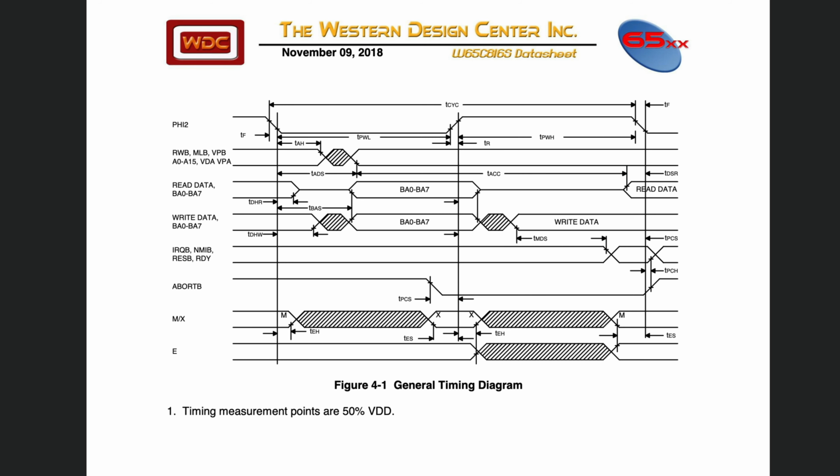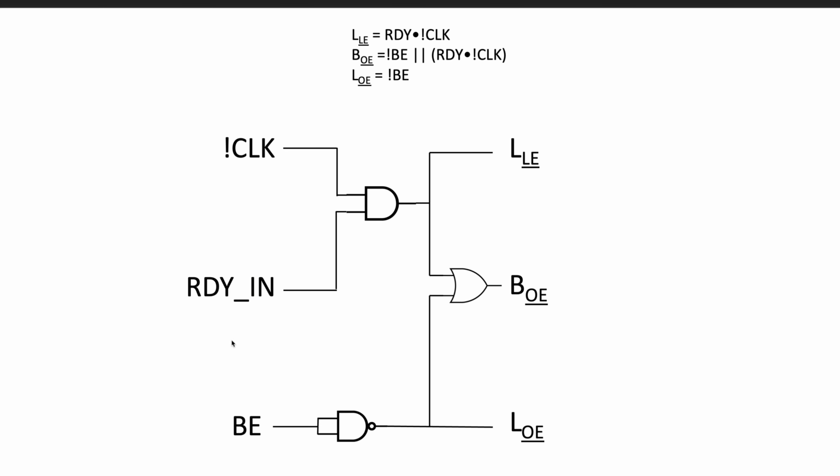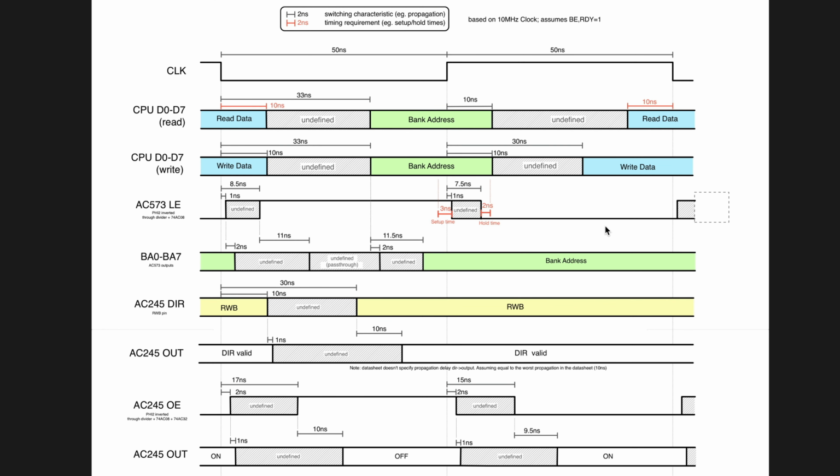But the way our control logic is done, even if the CPU doesn't pick up on a change because we did it too late in the clock cycle, the control logic will still be impacted because there is no timing consideration here. Moreover, we also don't want ready to be changing in the first part of the clock cycle, because the CPU will be sampling it at the end of the clock cycle, and so only the next cycle will be impacted.